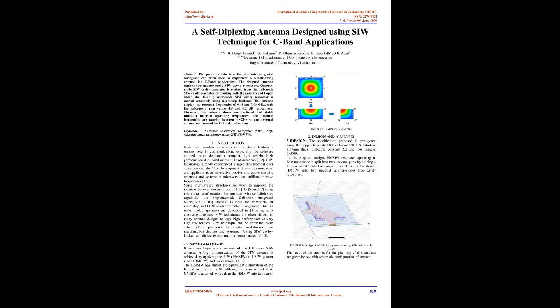Quarter mode SIW cavity resonator is attained from the half mode SIW cavity resonator by dividing it with the assistance of one open-ended slot. Each quarter mode SIW cavity resonator is excited separately using microstrip feed lines. The antenna displays two resonant frequencies of 6.44 and 7.09 GHz, with the subsequent gain values 4.8 and 6.2 dB